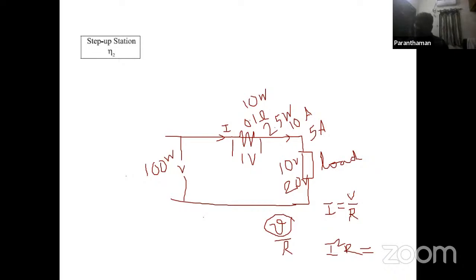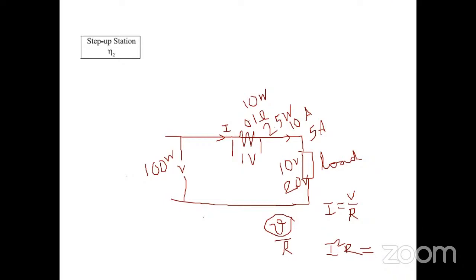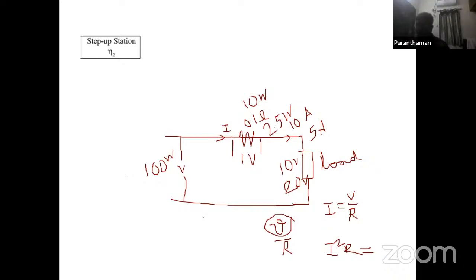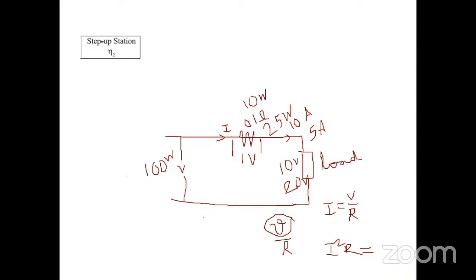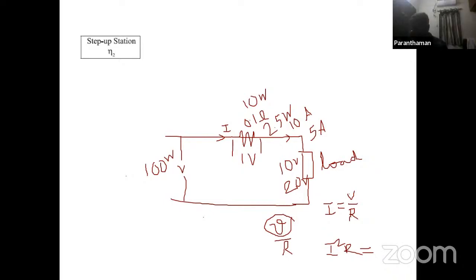And lastly, you put 0.995, right? Correct, sir. And then for 11 kV, you put 0.95. Again, it goes to a consumer. For an HT consumer, the transformer efficiency will be around 0.95 only, so we have to multiply it with 0.95.